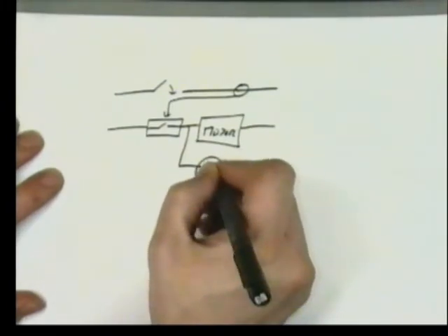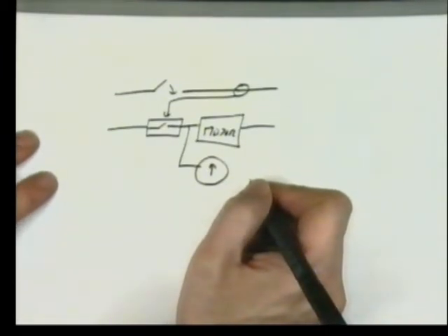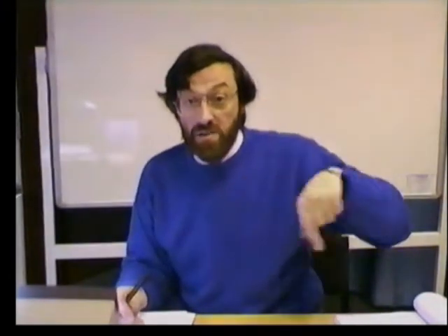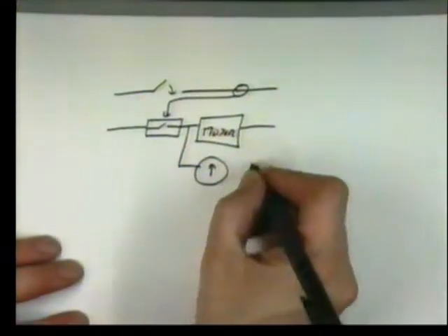when that switch closes, start a mechanical timer? And literally, these are mechanical timers. You'll find them in lampposts. They turn lamps on and off at the right time of day or night. It's not done by detecting the lack of sun. There are inside ordinary lampposts things called solar dials, which are just 24-hour mechanical timers. And as they rotate around, as in, you can see these sometimes in the home, in some very low-cost, cheap mechanical day clock timers. They're just mechanical, and as they move around, eventually a brush hits a contact, and it switches on a relay. So why don't we start a timer off as well?